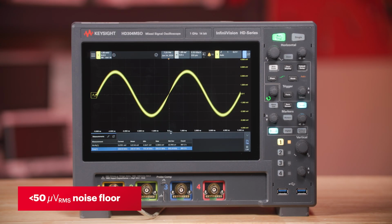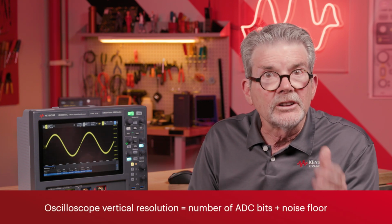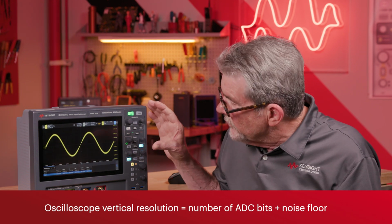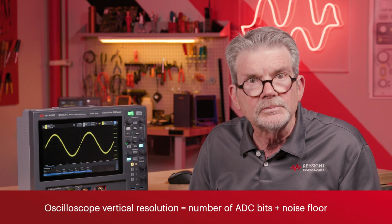The HD3 oscilloscope has a baseline noise level of less than 50 microvolts RMS at the scope's full 1 gigahertz bandwidth. Oscilloscope vertical resolution is not just a function of the number of bits of the ADC. It's a combination of the ADC bits plus the noise floor of the scope, which comes into play when viewing low-level signals at very low volts per division settings on the scope.